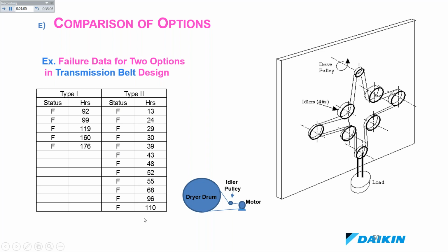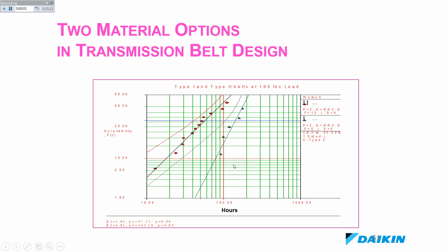They all failed. And then the new supplier came, and they said theirs are more robust, they survive better. I got only a few samples, put them into the same test fixture and got my results. Then I put them into a Weibull plot. And right away, I have a winner. So I know I should be changing supplier, not for cost improvement, but for quality improvement, design life improvement.